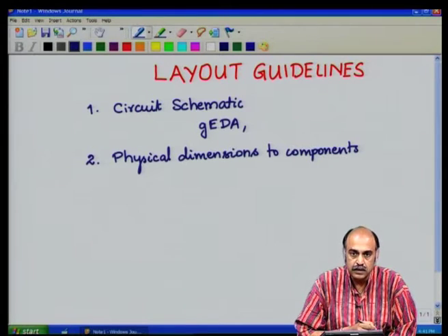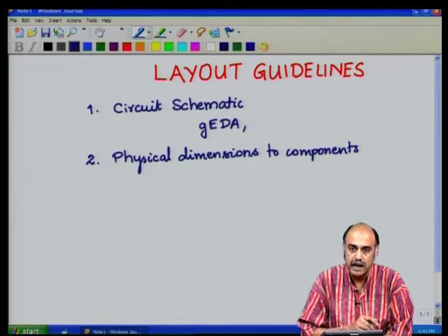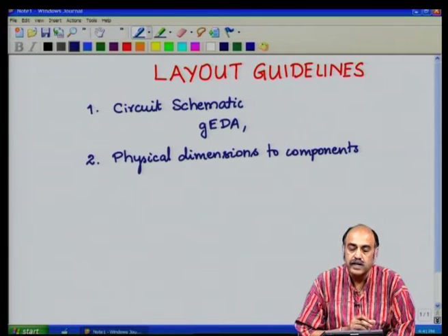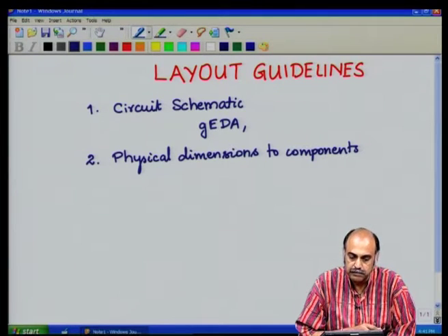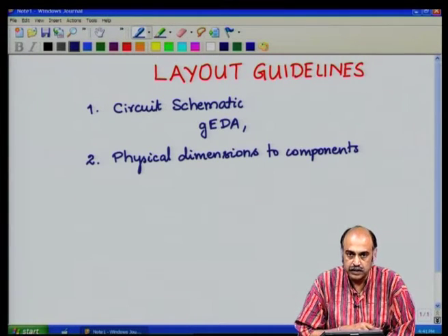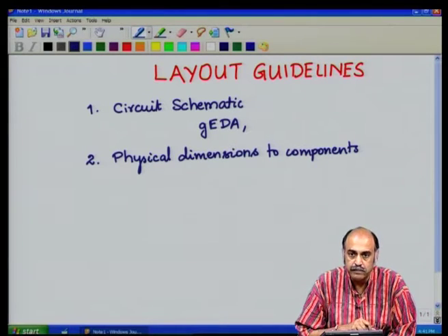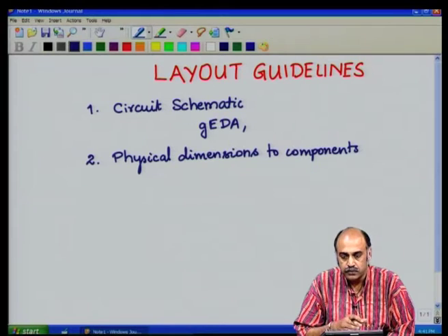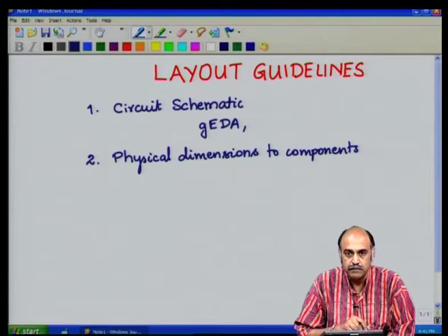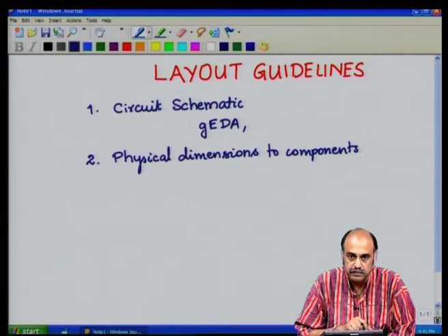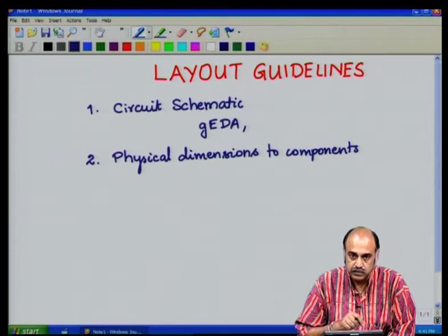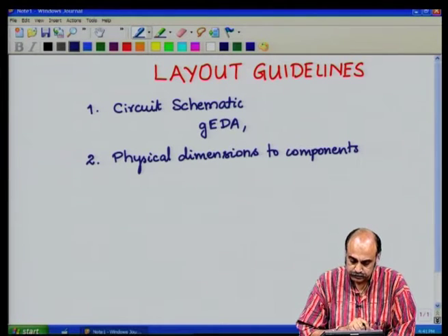Footprints basically map the electronic symbol or the electrical symbol to a physical symbol, that is, it would map probably an op amp which has the electronic symbol into a physical symbol containing probably a dual inline package or an SMD package, one of these which has the leads coming out of the integrated circuit package.